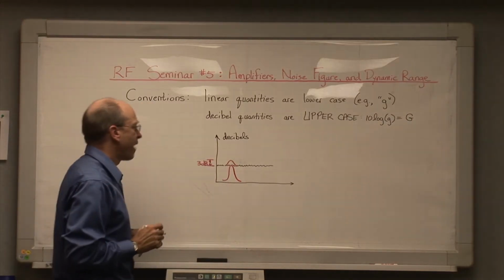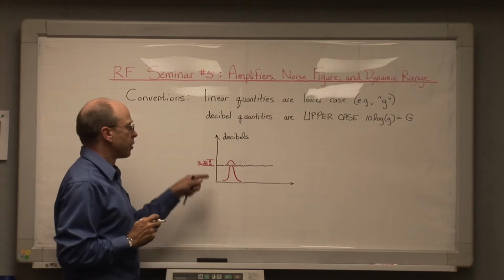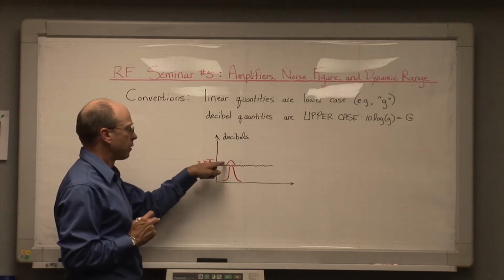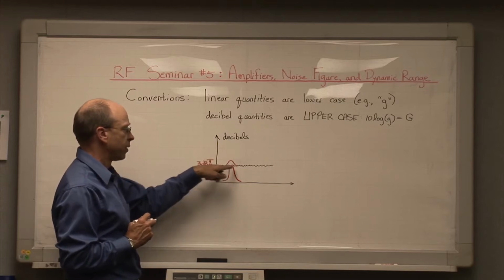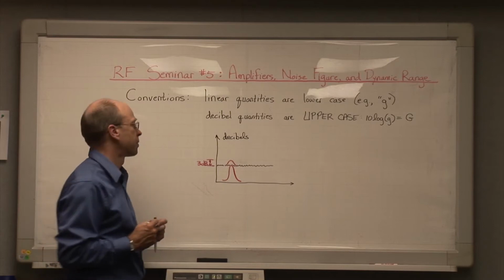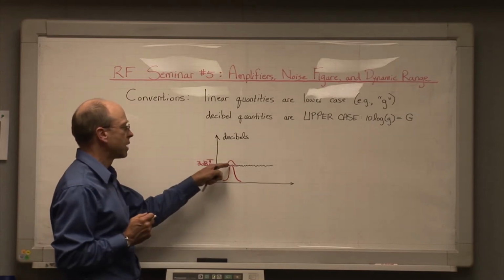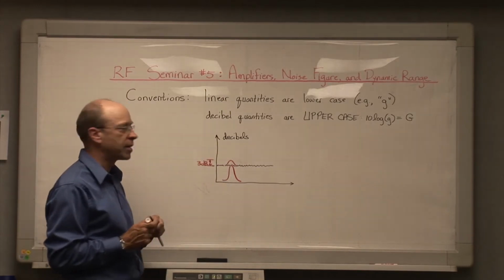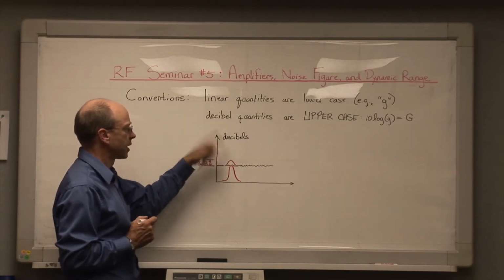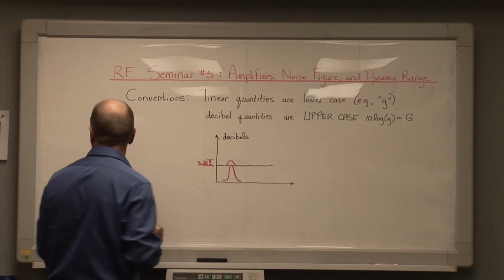And we remember that we have to be cognizant of the fact that if we're using a measurement system and we see a signal that's, say, 3 dB out of the noise, that means that its real power level is in fact equal to the noise power. And you can do the math, of course, for other values like, say, 1 dB out of the noise or 4 or 5 dB out of the noise. We don't have to worry about doing any kind of a correction once we see the signal 10 dB or more out of the noise approximately.